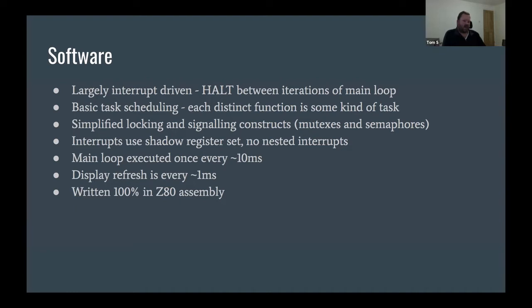As a result, nesting interrupts would become very difficult to achieve, because you would have to determine, have I switched to the other register set already? Do I need to back up any registers? And to be honest, there really aren't that many interrupts going on anyway to need to worry about.